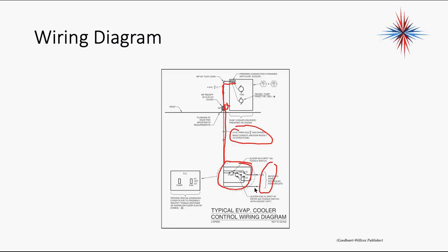Because in most jurisdictions, you are only allowed to touch the equipment from where the power connects to the equipment or to the junction box, depending on the jurisdiction. You are not allowed to run the wire back to the switches or the breaker panel. That's the electrician's job. That's the standard. Now, some states allow differently, but in most states, the electrician is responsible for getting it to the closest junction box on the piece of equipment. Does anybody have any questions on that?